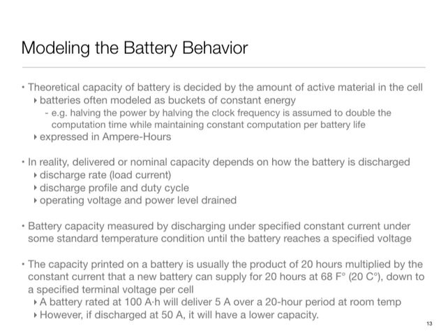So there is a theoretical first order model, which would be that a battery is a bucket of energy, and every time I draw certain power, I integrate over time. So what this would suggest is that if I'm trying to design a system, and I have modeled my processor and the rest of my system, its power states, and I know what power state it was in, then I essentially have to do an integration of current over time, and every time I change the state, my current number changes, and at some point the system would die because my integral of I(t) dt adds up to the energy which the battery had.